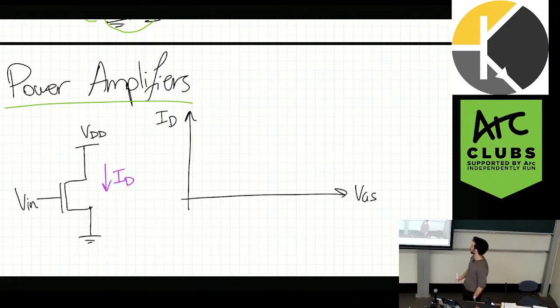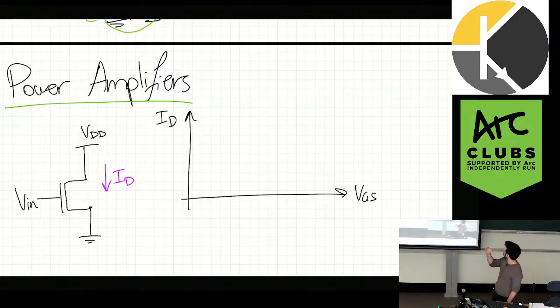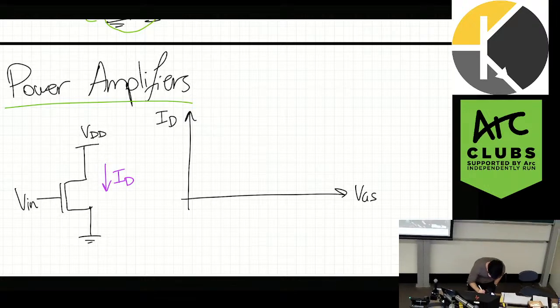Now the source we always consider in an NMOS as the lowest potential because, again, the channel is full of negative charges. Again, this is just semantics and definitions. And obviously the lower potential, or where the negative charges come from, is ground, right? It's not going to come from the power supply. So we consider this as the source of negative charges. So V in minus V source would be 0. So then this is just V in.